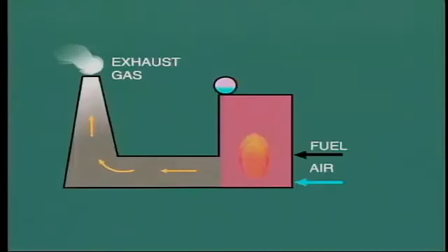We've already mentioned that some heat loss is involved if we provide insufficient air for complete combustion. But we must also pay a penalty if we provide too much excess air. Now, why is this? Well, all of the combustion gas which leaves the chimney and exhausts to atmosphere carries with it a certain amount of heat.